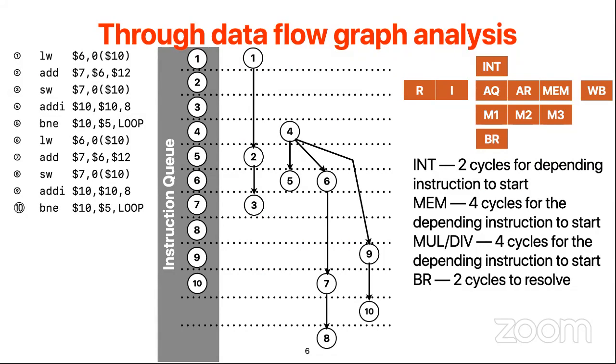register renaming. Because register renaming eliminates all the false dependencies, after renaming you are only seeing true dependencies in your code. So you can imagine your processor is now scheduling your instructions whenever the data dependencies are resolved. In this way, how many cycles it takes to empty out the pipeline becomes relatively straightforward: you just look at the data flow graph and you are able to know how many cycles you need to execute all the instructions.